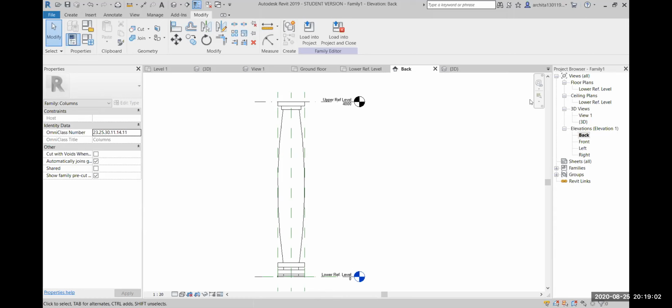This is basically like the circular one, different, you know how this table has been created. Create different work planes. In every work plane, give the sectional profile of this table, the curved sectional profile of this table, and then choose all of them and create a form out of it. Can you show, ma'am? I have to cover other topics. I'll do one thing, Karthik.